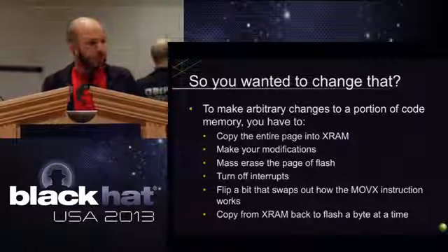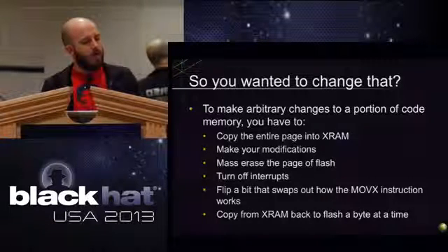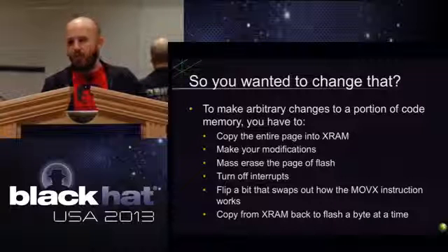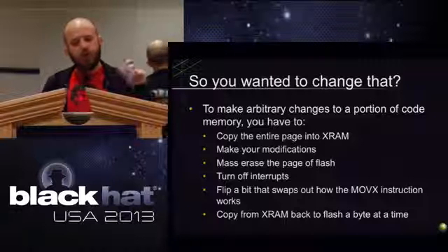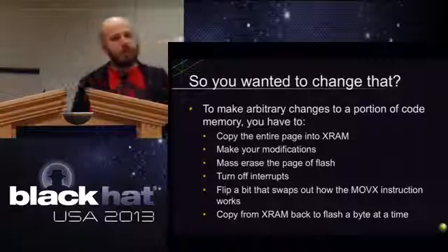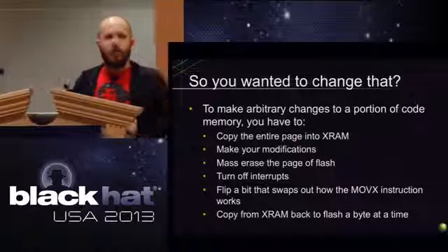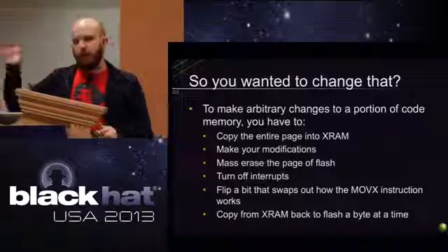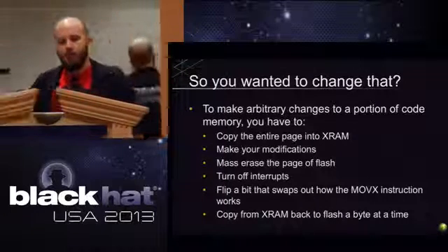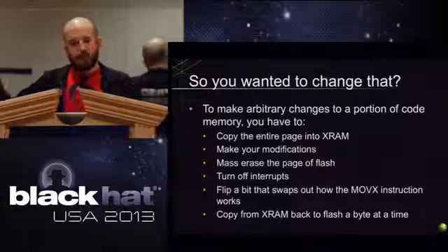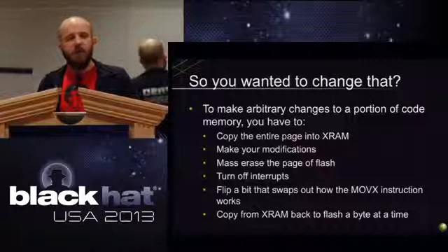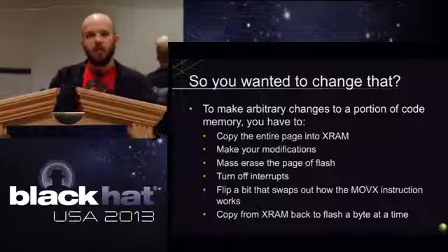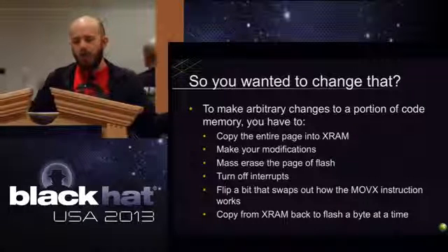The way this particular Harvard implementation works, like I mentioned, is that normally you can never modify the code page, you can never modify Flash. The way it works is there's this movex instruction, which normally means copy data to or from X data, a very particular section of memory where all the data is stored, like all your variables and all that kind of stuff, not code. And you flip a certain bit, and suddenly that same instruction now makes a modification to the Flash memory.